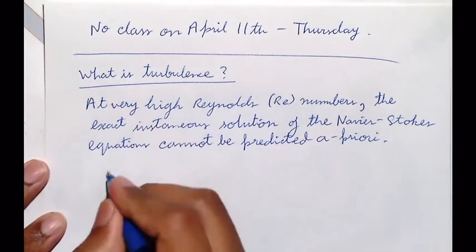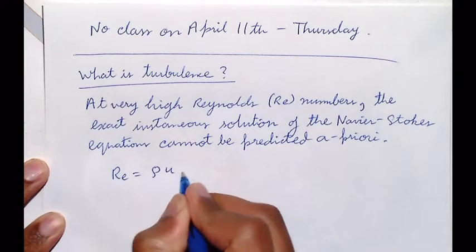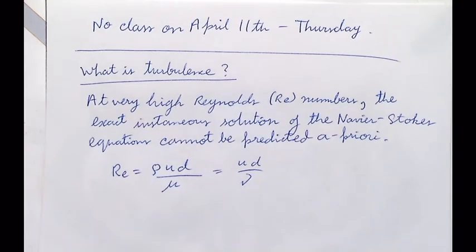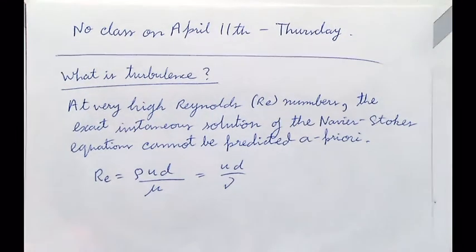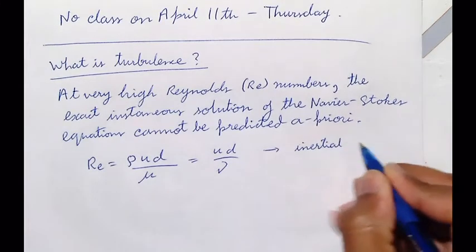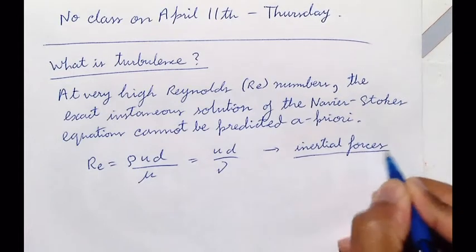So first, Reynolds number. What does the Reynolds number mean? Re equals rho U d over mu, right? So what does this represent? It's a non-dimensional number, fine, but why do we care so much about this? Do you know physically what this number gives us an idea of? Ratio of convection terms to viscous terms. Yeah, exactly. So this is a ratio of inertial forces over viscous forces.